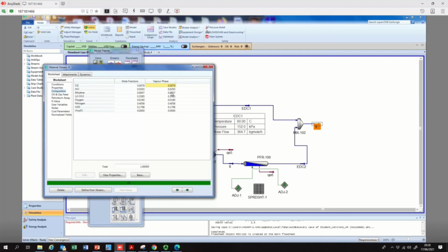I need to check my notes for a second. I hope you already have those key sheets which I asked you to write. What we are going to do is add a small flash column, and we are going to maintain the flash column temperature at 15 degrees centigrade. At 15 degrees centigrade, your water and all the liquid products, like ethylene dichloride, are going to remain in the liquid phase.